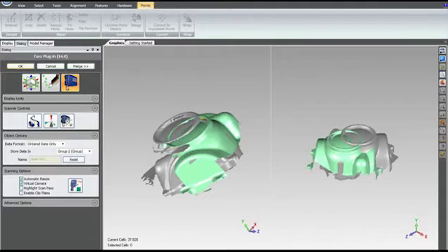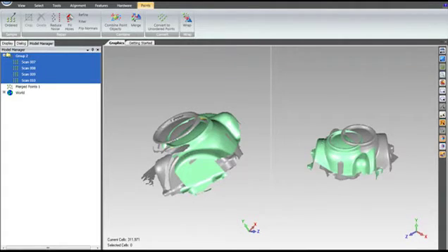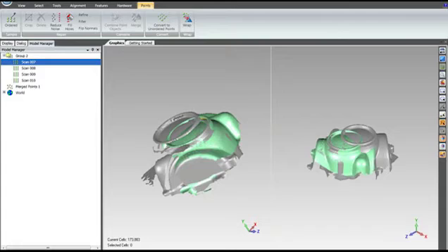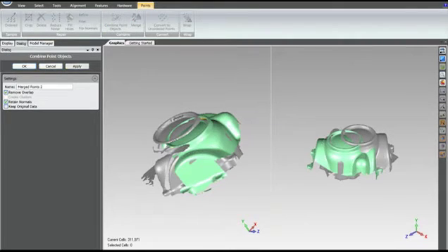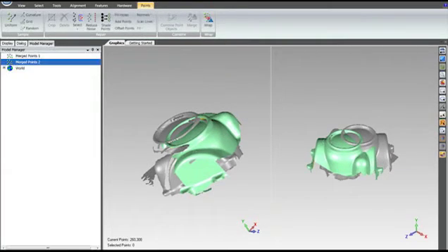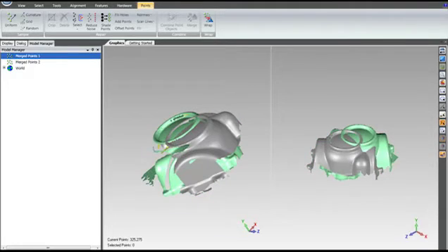Select OK to close the FARO plugin. Choose the scans from the second half of the part and merge those as you did for the first ones. Choose Combine Point Objects. Select Apply. And select OK. Now we have two objects and we want to align these two.